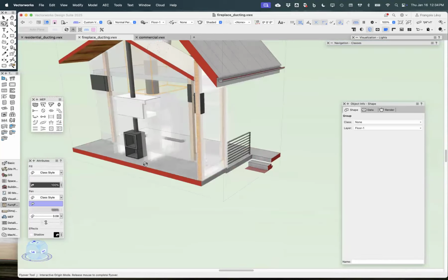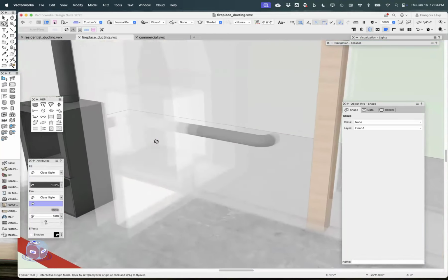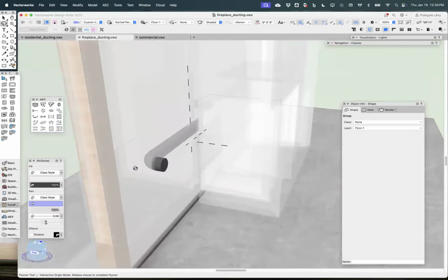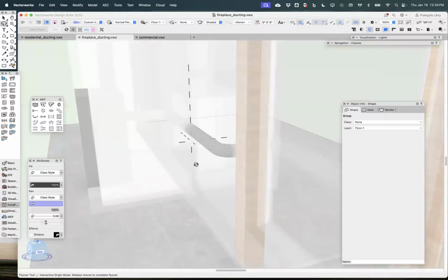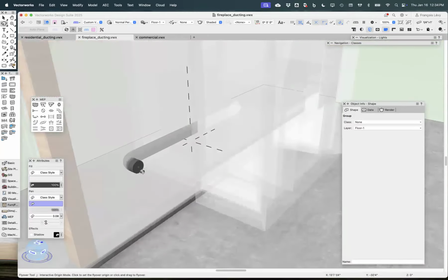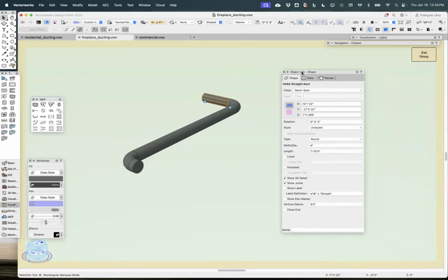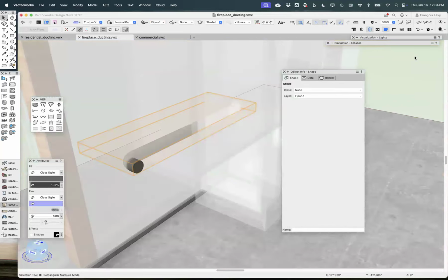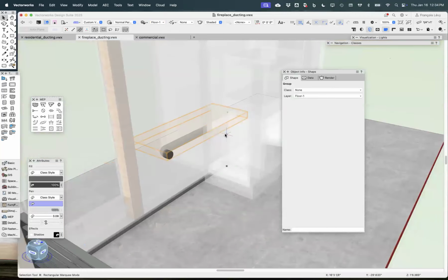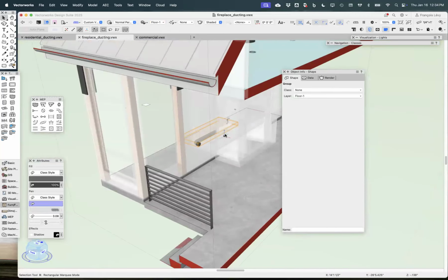And then the stove also has an air intake. And so we, again, use a series of little ducts based on the manufacturer rules on how far it could go, how many 90-degree turns. So here you go. There's an HVAC straight duct. It's 4 inches in diameter. Here's an elbow. It's 4 inches in diameter with a 3.5-inch inner radius. There's another duct, another elbow, and another duct, so that we can see just exactly how this thing is going to vent through the wall without having some ugly pipe.